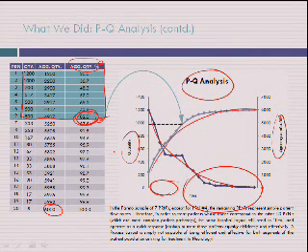I'll discuss that later, but the method is PQRST. P stands for products, Q stands for volume, R stands for routing, S stands for sales or profit margin, and T stands for demand stability: runners, repeaters, or strangers. We need to look at Q, R, S, and T before we decide how many businesses the job shop is trying to operate under one roof.